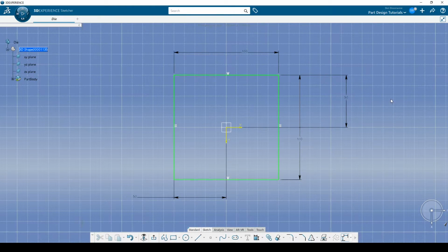And now I have a centered rectangle, and it's fully constrained. So when you look at this, you see it's all green. It's all green, and there's actually a point in the center there that you can't quite tell, but if you could zoom in you would see that it's green also, because everything is locked in place. They call it iso-constrained, as in equally constrained everywhere, and it can't move.